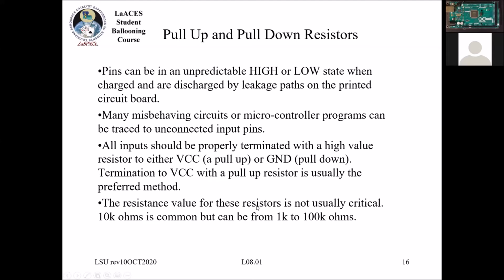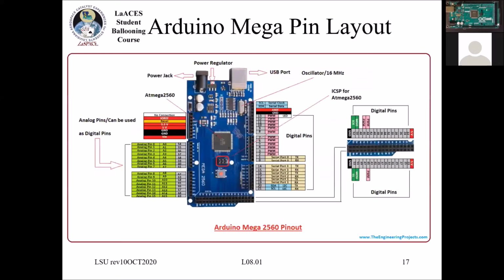So basically anything from 1 to 100 is okay. There can be impacts depending on what sort of circuit you actually connect to the I/O pin if you start worrying about timing, but that's something to worry about when you're designing that circuit.